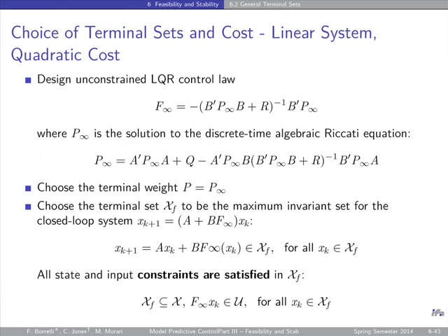Okay, this is the linear system. When you apply the unconstrained LQR, the linear system was Ax plus Bu, u is F infinity xk. So this becomes now an autonomous system, a system without inputs. This is the closed loop system. And I will ask the software, compute the set, the largest set XF, such that when I start in there, I will be in there at all time instances. There is a typo here. This is F sub infinity times xk, right?